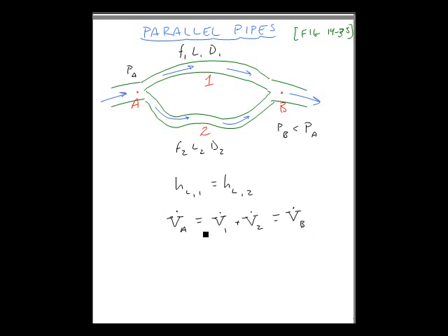So this is what has to happen for parallel pipes. If this situation does not exist, then you'll just have flow going through line 1, and flow 2 will be static or just stagnant. It will be like one of the offshoots on the Hudson, where this is the main river and this is a marshland, if you will. So, a bad analogy, I agree. But if you don't have the same pressure drop through the lines, they're not going to recombine and move forward together.